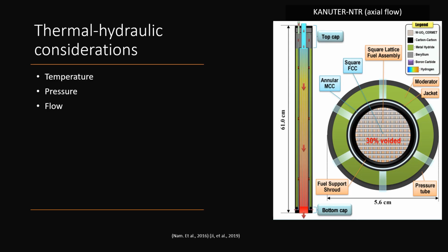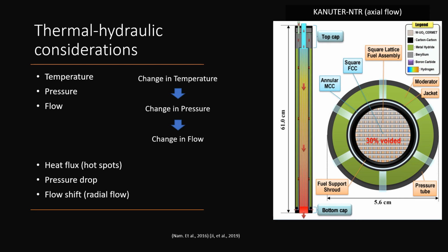So, thermal hydraulic considerations in NTRs, we concern ourselves with temperature, pressure and flow. Where there's a change in temperature, there's a change in pressure, there's a change in flow. Or we can say, where there's a change in one, there will be a change in all. The issues presented through thermal hydraulic considerations could be heat flux or hot spots in the reactor core, a pressure drop of the hydrogen, or flow shift, typically seen in radial flow designs.